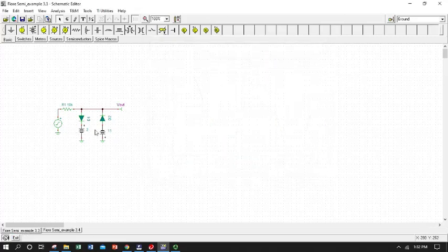We don't have to have these sources. We can just use the forward bias voltage of the diodes themselves, in which case we would have a curve that just swings back and forth between V forward, positive and negative, which isn't quite as useful as having it adjustable.